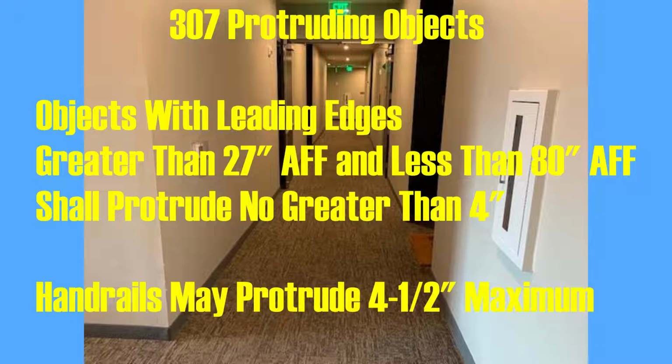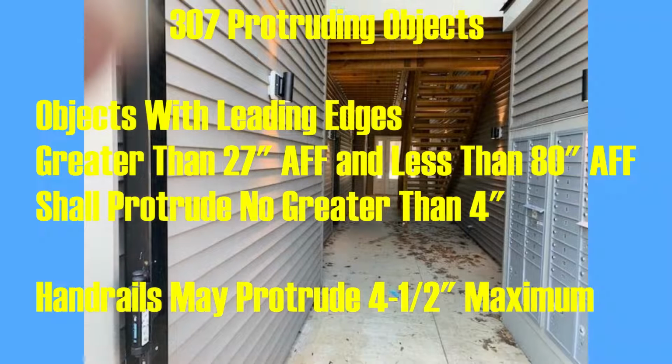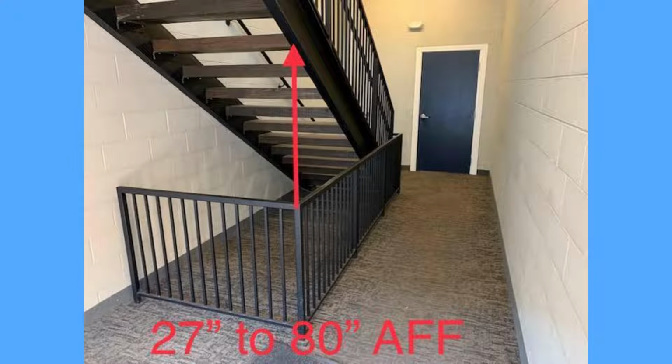Section 307, Protruding Objects. Objects with leading edges greater than 27 inches above finished floor and less than 80 inches above finished floor shall protrude no greater than 4 inches. However, handrails may protrude 4.5 inches maximum. Section 307.4, Vertical Clearance. Where vertical clearance is less than 80 inches above finished floor, guardrails or barriers shall be provided.